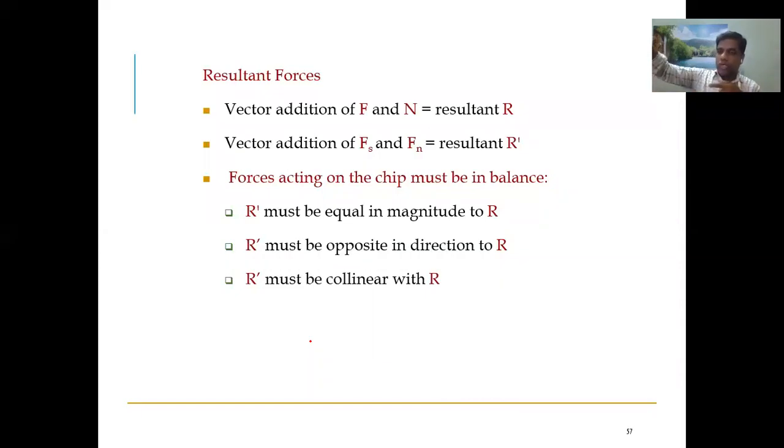It means it is forcing your workpiece out of your jaw. Even it is forcing your cutting tool away from your workpiece. So the cutting tool may break. So that's why the forces are not in the same direction. The forces are in opposite directions, same magnitude, opposite direction, and must be collinear.